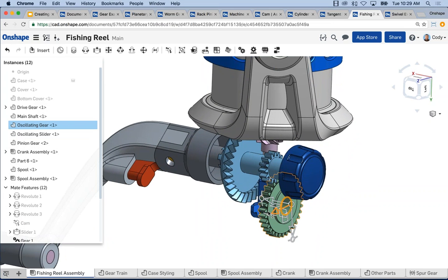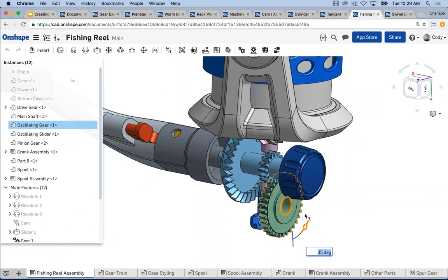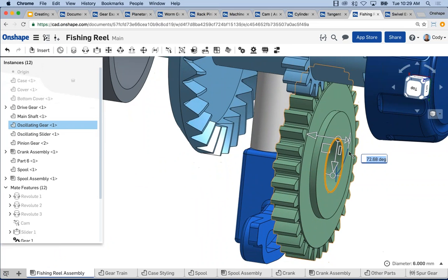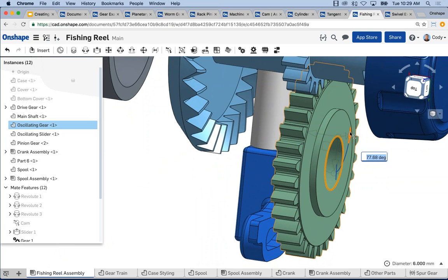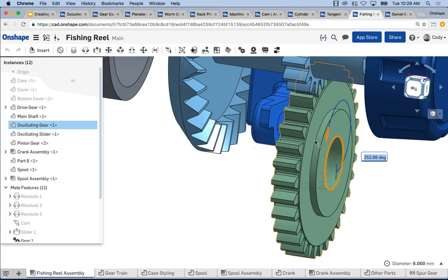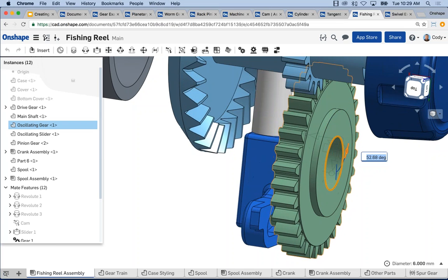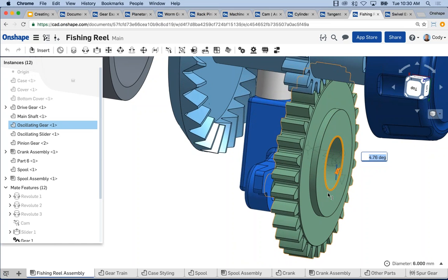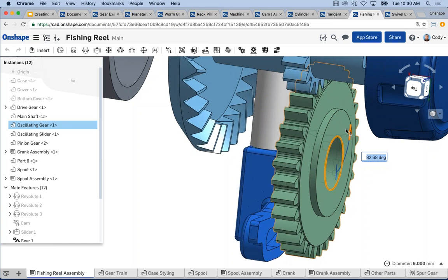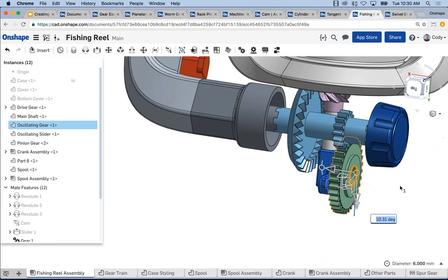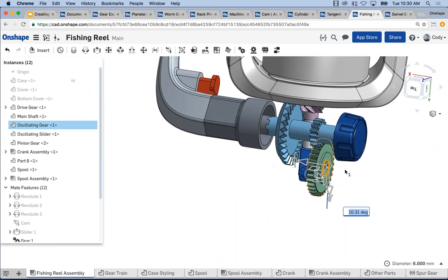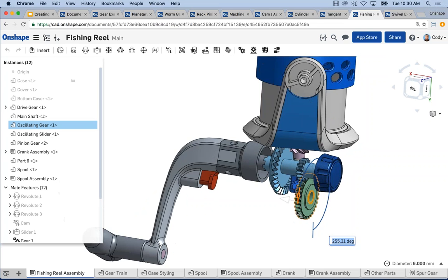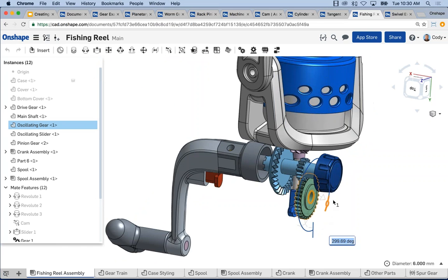And if I were to drive one of these parts, let's say rotate it around, you'd see that the tangent mate is maintaining that relationship between the blue part and that pin in my gear. And as it spins up and down, that's what's giving me my linear actuation for it. Right. So again, it's just maintaining inside of that groove and following that consistent path, but combined with the rotation of the gear gives me that up and down movement that I expect to see from the spool.